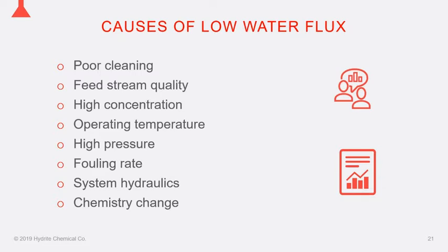So the remedy to that is to review the cleaning program and check everything and make sure the pumps are working, make sure that the levels in the drums are dropping as you would expect from the surveyed chemical usage amount, okay? The other reason a system could be dirty is they have a feed stream upset. The feed stream quality all of a sudden takes a dive, or they get a process stream from a different supplier. They could have denatured protein. All kinds of things can happen. They could have extraneous material that they're not expecting in their feed stream. Or if they changed water supplies, they went from city water to well water, and the well water could have some type of foulant in it, okay? All these things can happen, and they are all causes of poorly cleaned or still dirty membranes.